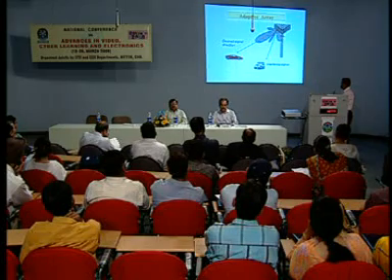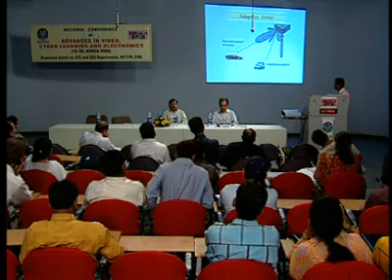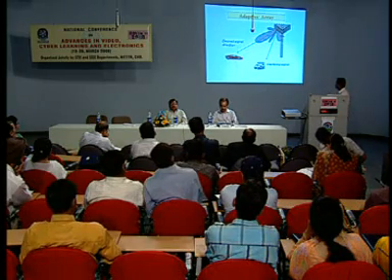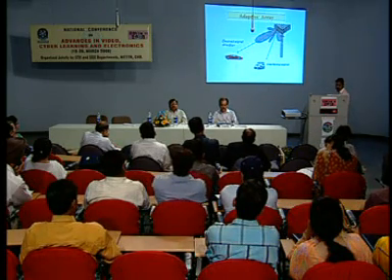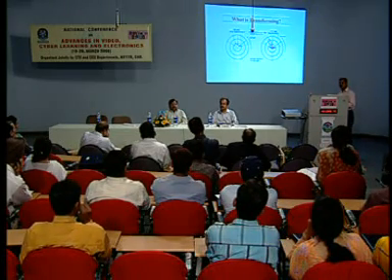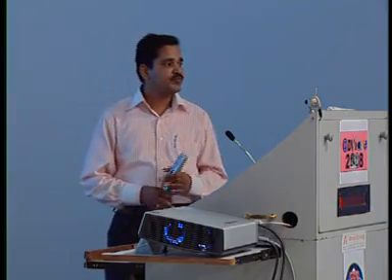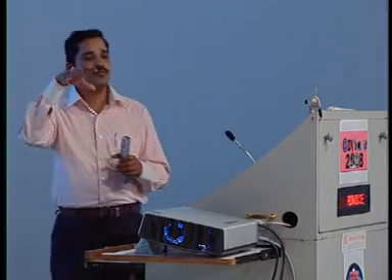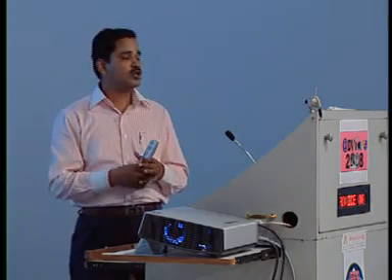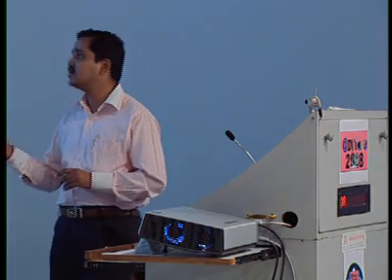So by changing the signal processing behind the antenna, you can relocate or reorient the radiation pattern of the antenna. Now what is the job of your smart antenna? First it finds out in which particular direction your desired signal is coming from.